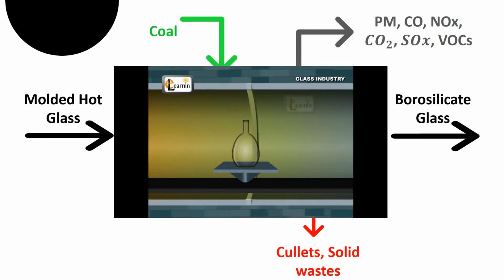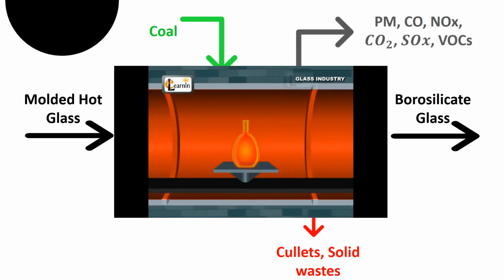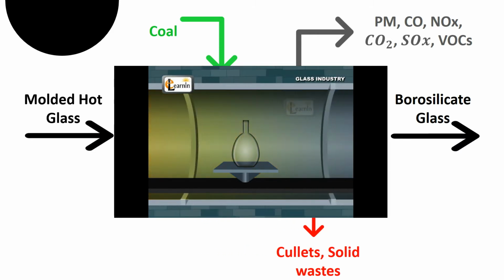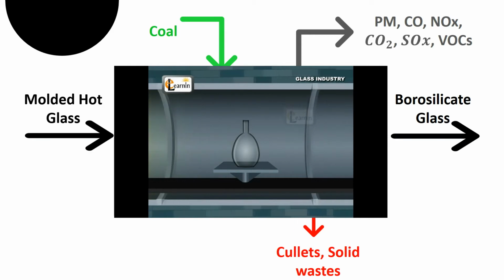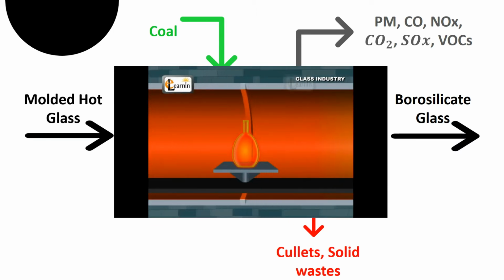The three stages of the annealing process that proceed as the temperature of the material is increased are recovery, recrystallization, and grain growth. The first stage is recovery, and it results in softening of the metal through removal of primarily linear defects called dislocations, and the internal stresses they cause. Recovery occurs at the lower temperature stage of all annealing processes, and before the appearance of new strain-free grains. The grain size and shape do not change.